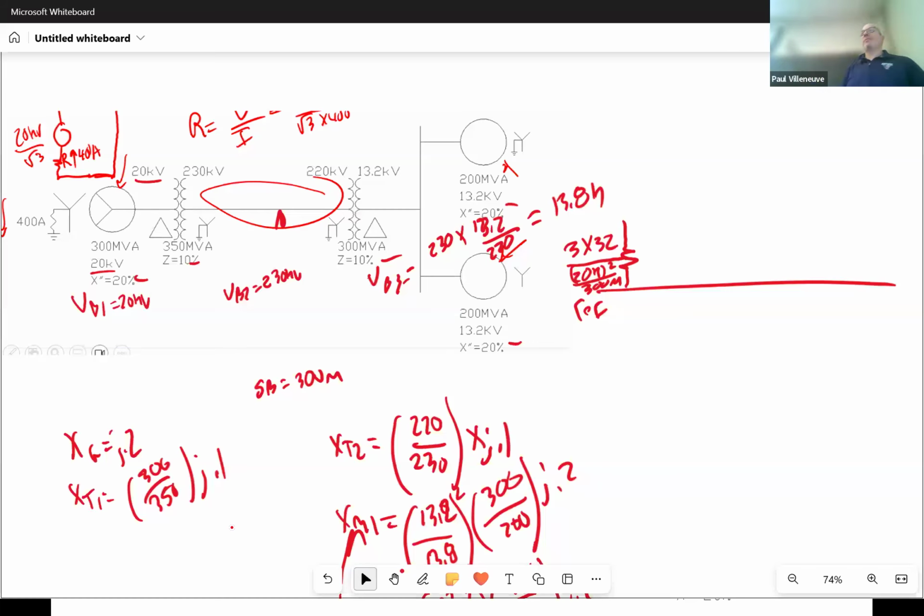This is a per unit representation, right? Why would you put 32 ohms in there if everything is in per unit? Close. You think you get a good result if you put in 96 there? One, we saw when we looked at load flow, you had a sign change and it wouldn't converge. Can you imagine the wonky results you would get if you put 96 ohms in there? You get some pretty goofy results.